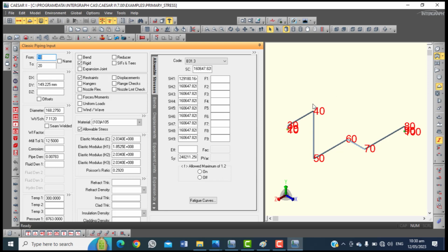It is almost impossible for me to put a support at this point, though of course this depends on the other existing equipment and elements close to this pipe. But for now, I want to concentrate on what we have here. At 38, I already have displacement up to node 70.